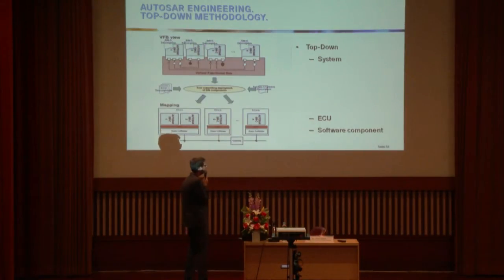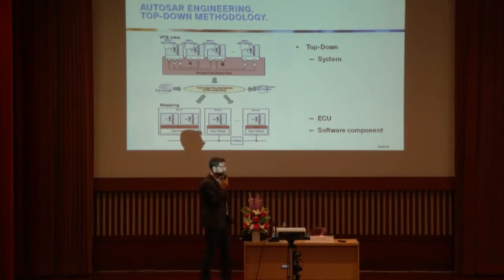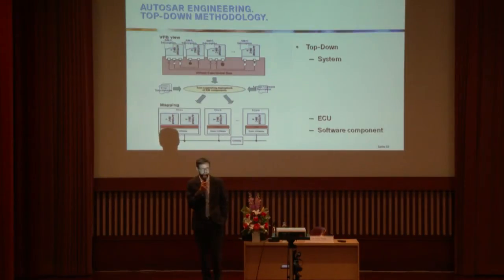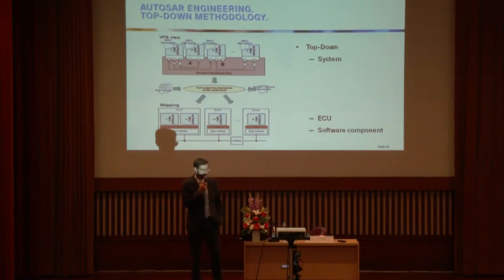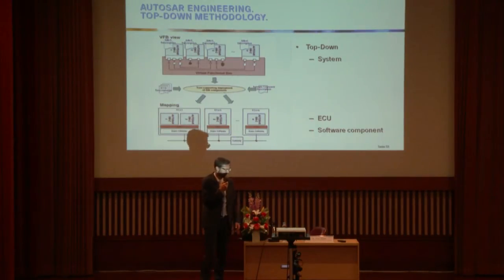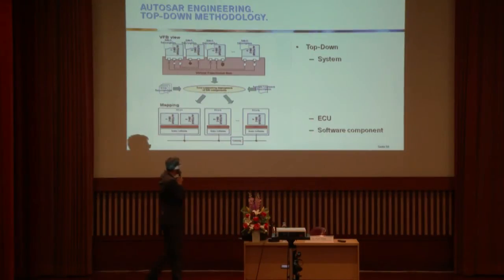And in the next level, when you map your software components to specific control units, you get the derived communication and automatically get the runtime environment I mentioned, which is shown here in red. So this is responsible for the communication, and this is generated automatically out of the information which you see from the virtual function bus.